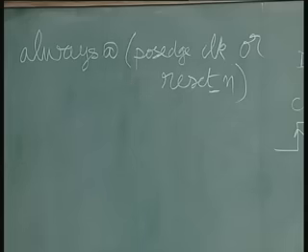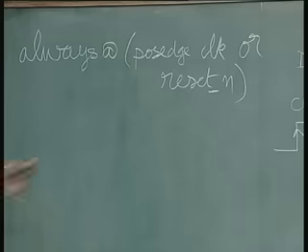And why this reset underscore n, why should we go for low, is that if you make a big system, this reset will be residing as a master reset on a control panel, and you need to reset from there, and that will be connected via a long cable in general.